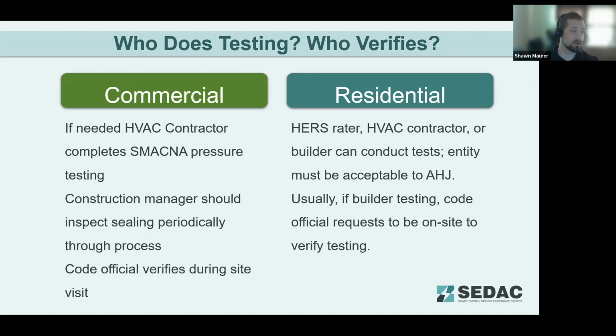And as noted before, there is an exception if all your ductwork is within the thermal envelope. The duct leakage testing is not required, but the duct sealing is, and that does still need to be verified. So again, especially if you're hiding ductwork in a soffit or somewhere where it's behind drywall and not easily viewed, you may want to coordinate with your code official to come out and do that duct sealing inspection. Even if all that ductwork is within the conditioned envelope, they do need to verify that the sealing has been done, even though there isn't a pressure test required.